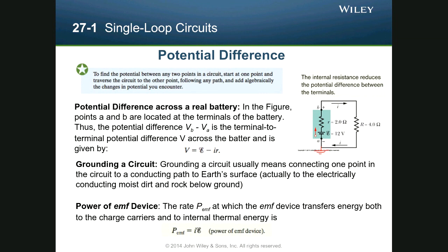It's the symbol with the three lines that I just drew. So what this does is you're connecting it to something that is grounded, and you're ensuring that this voltage is physically actually 0. Right now it's been abstract and we can set it to anything we want. But if we ground the circuit, then the negative terminal goes to ground, so we know that we have 0 potential at that point. And if we were to measure it, that's what we'd get.